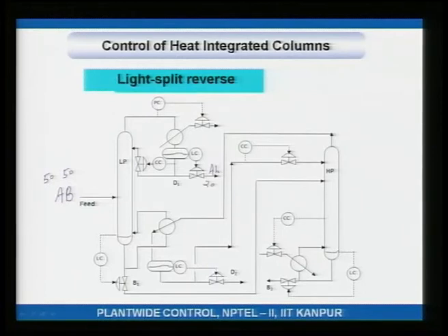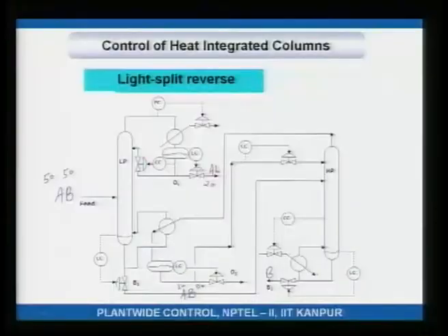Okay. So, then the bottoms is an AB mixture. This is the bottoms from which column? Yeah, from this column. This is an AB mixture. This is sent to a high pressure column, and now this would be 20 has been taken up. This is actually only 30 kilomoles of A per hour and 50 kilomoles. Okay. So, the stream to the HP column has relatively lesser amount of A. Okay.